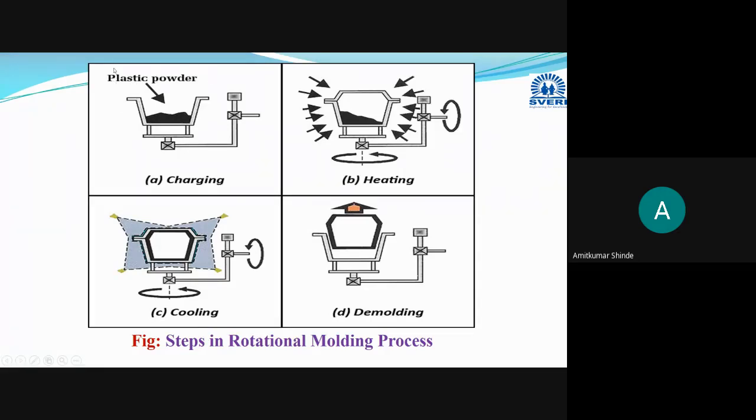Then this mold cavity is closed in the second stage, and it is heated. Okay, here in this second stage, we are heating it, and we are rotating this mold cavity. Okay, through these two arrangements.